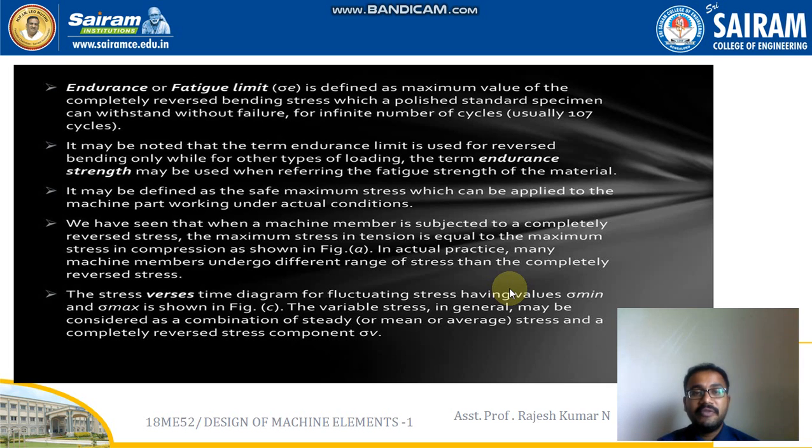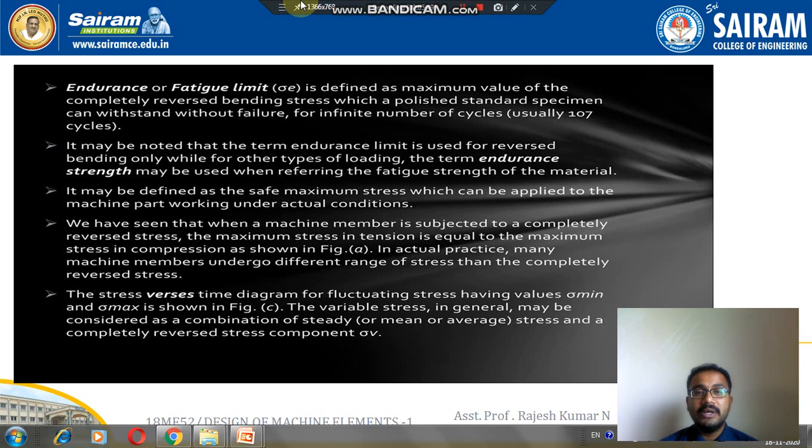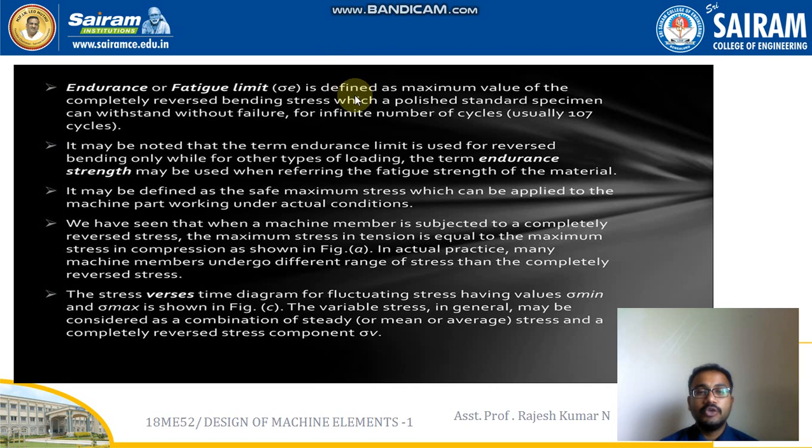So, the endurance or fatigue limit is defined as the maximum value of the completely reversed bending stress which a polished standard specimen can withstand without failure for an infinite number of cycles. Usually, 10 power 7 cycles is recommended. It may be noted that the term endurance limit is used for reverse bending only, while for other types of loading, the term endurance strength may be used when referring to the fatigue strength of the material. It may be defined as a safe maximum stress which can be applied to the machine part working under actual